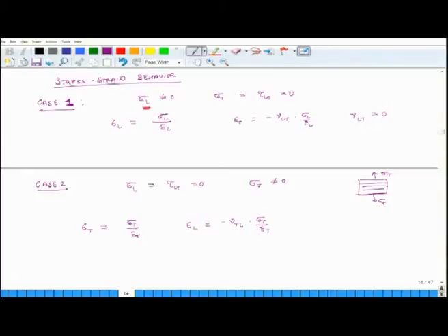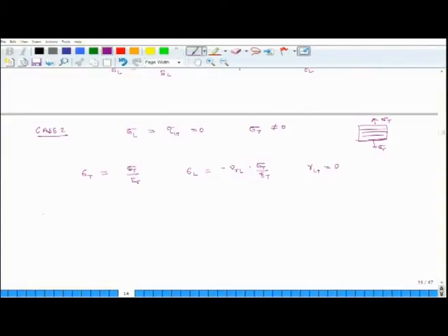Okay. So, here also the loading is aligned with the axis, here the load is aligned with the transverse axis, and so I am just applying a pure extensional strain, and because it is the case of special orthotropy, there will not be any shear strain gamma LT. So, gamma LT will be 0. The third case is that of a pure shear stress.